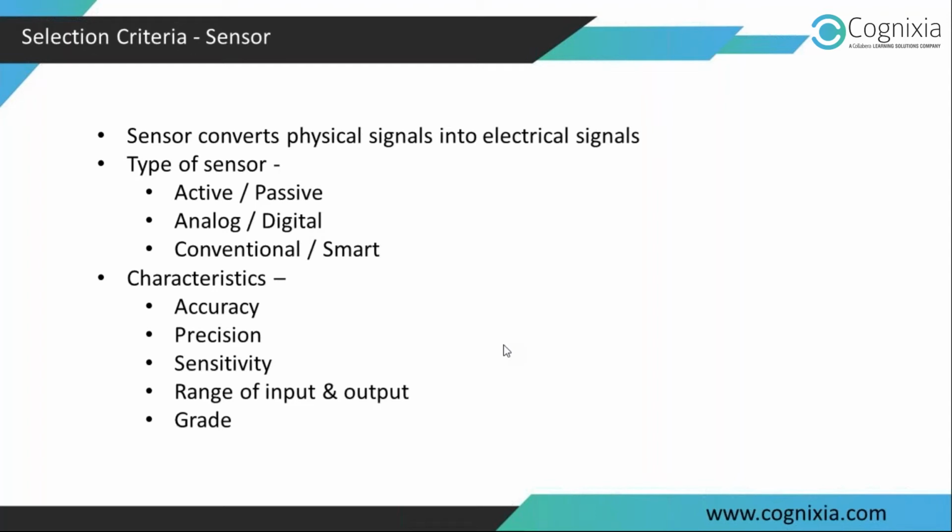Okay, then we have conventional sensors and smart sensors. The smart sensors are new generation sensors. Most of the time, these smart sensors already have microcontrollers embedded in them, and the data coming from them will come well formatted. Okay, conventional sensors are pure electromechanical systems. For example, a piezoelectric sensor, or a microphone. This type of sensors are called conventional sensors.